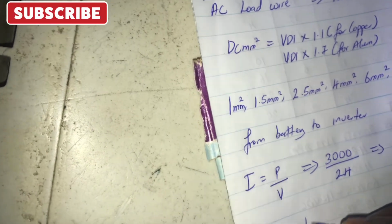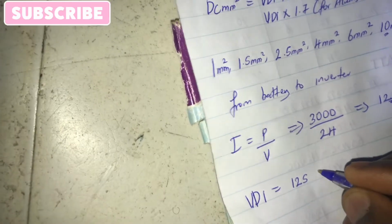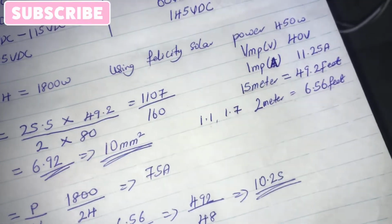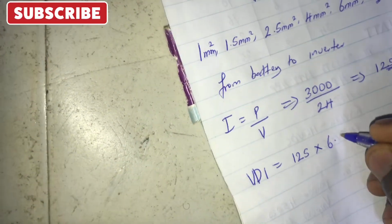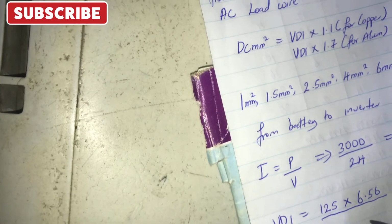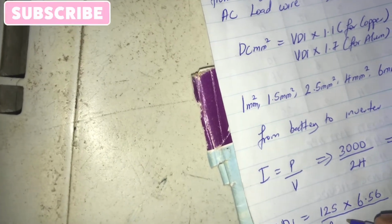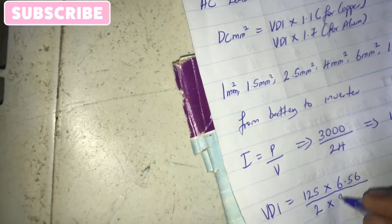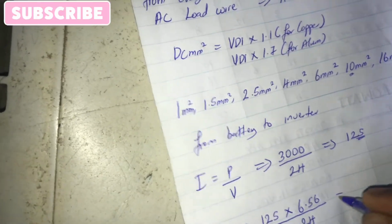This is our current, 125, multiplied by the feet. We'll still use the 2 feet, which is 6.56. 6.56 all over, we are still using DC, that's why we are using 2 multiplied by the voltage, which is 24, giving us 48.